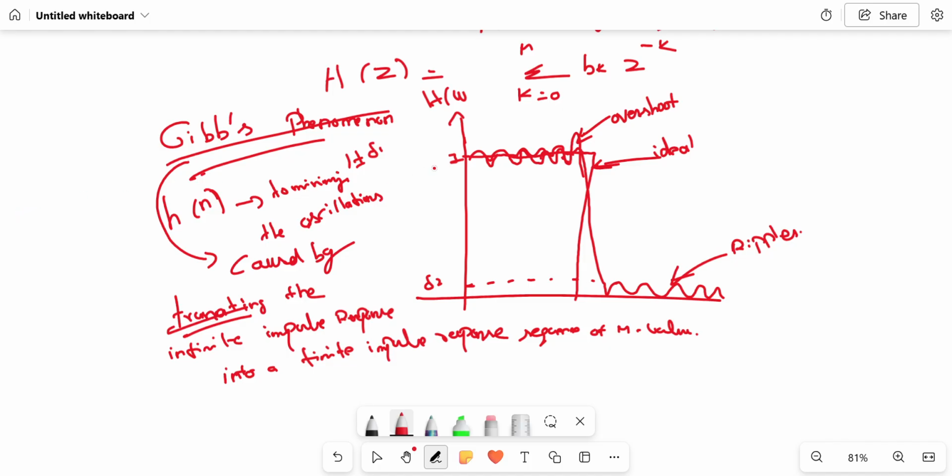The mathematical equations for the different cosine based windows we will discuss in the next session. The discontinuity, the oscillating behavior, the overshoot, and the spectral leakage are all more in the rectangular window compared to cosine based windows. So, various types of tapered windows, that is cosine based windows, can be used to reduce the sudden overshoot in the pass band. That we will discuss in the next class. Thank you.